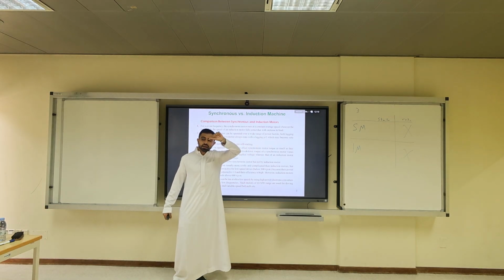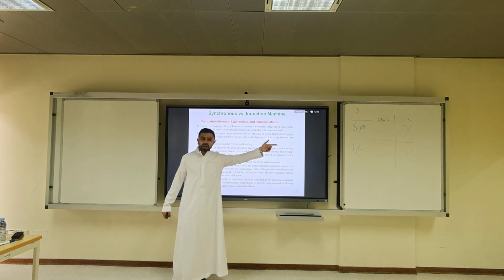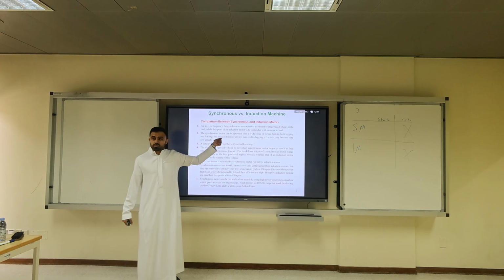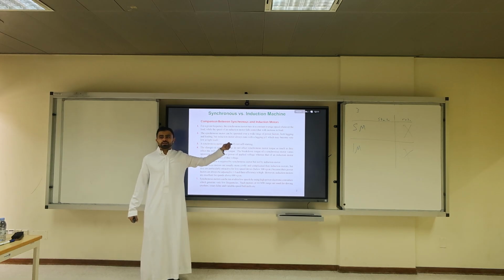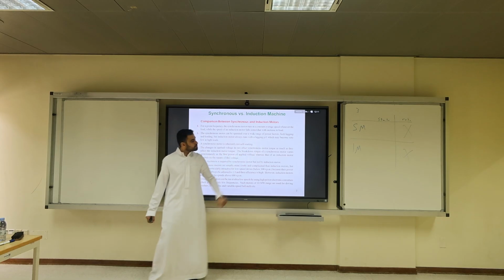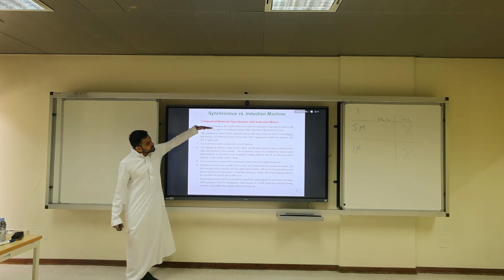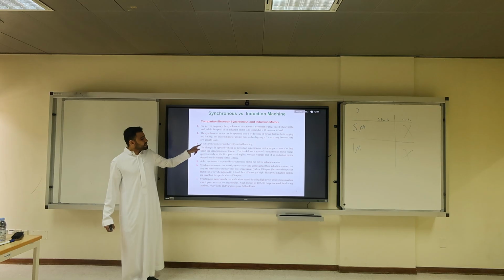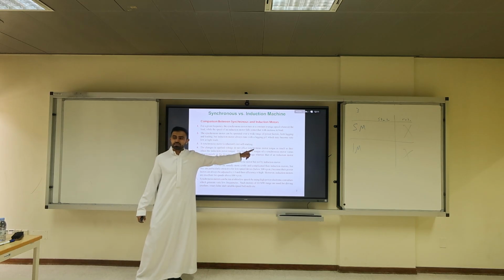It can be leading, it can be lagging, it can be unity power factor. But the majority of induction motors you run always at a lagging power factor. There is no under-excited induction machine. Okay? So, different speeds, different PFs, and the ability to self-start.